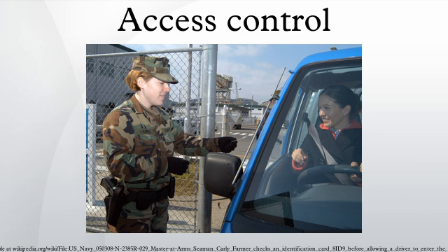Advantages: RS-485 standard allows long cable runs, up to 4,000 feet, and relatively short response time. The maximum number of devices on an RS-485 line is limited to 32, which means that the host can frequently request status updates from each device, and display events almost in real time. High reliability and security as the communication line is not shared with any other systems.